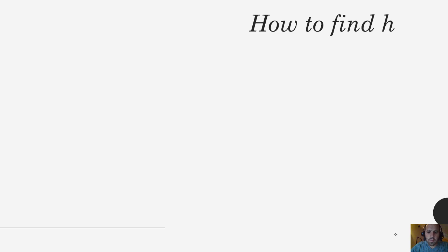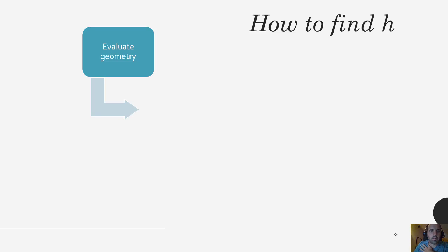So far, as we've talked about h, we've used it a little bit in energy balances and at the boundaries of conduction problems, and we've always treated h as if it's a constant. But as we discovered in the last chapter, h can be something that varies. So h is going to be a function of the geometry of the system, of fluid properties, and a few other parameters. So this is the basic procedure that we follow to find h for the next several chapters in the book.